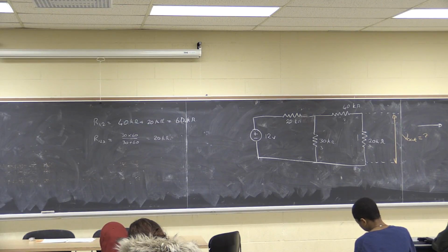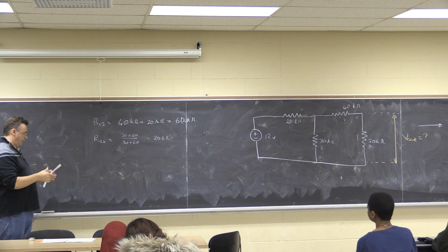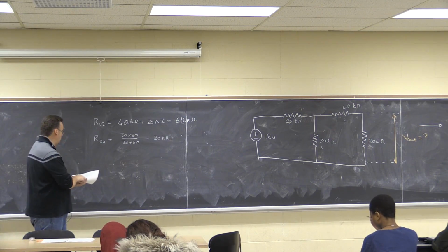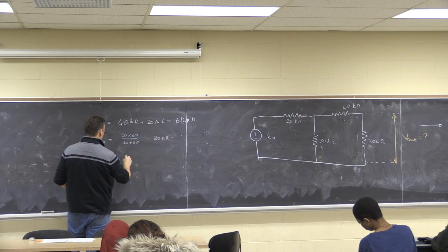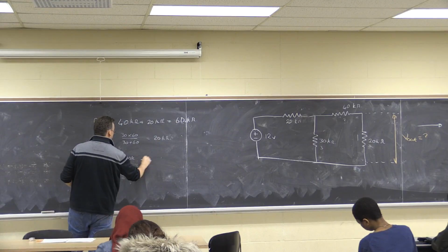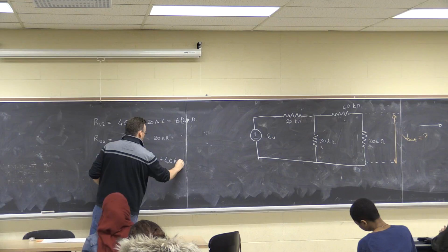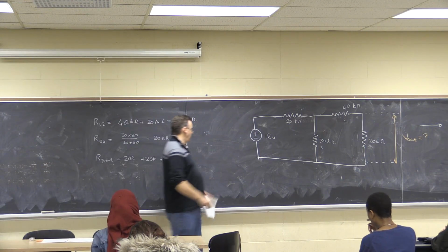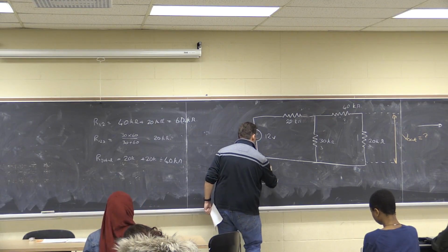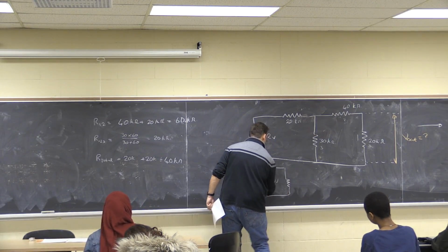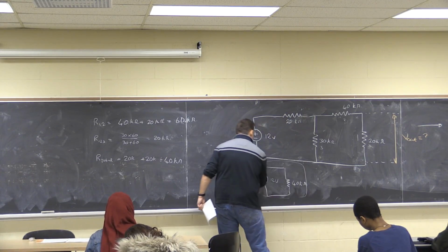Okay, using my trick of how to do 1 over, I can simplify that calculation. And finally, the final circuit, R total equals the 20k plus the 20k, which is the rest, equals 40 kilo ohms. So this circuit is the same as plus minus 12 volts into a 40 kilo ohm resistor. So that's the equivalent circuit.